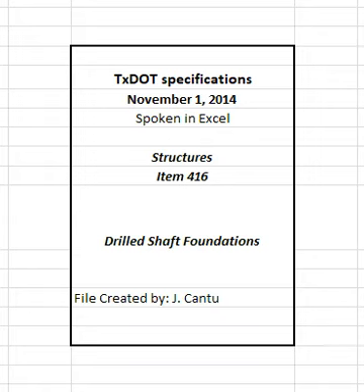3.4 Requirements for slurry displacement method. When soil conditions warrant, use the slurry displacement method to construct drilled shafts unless otherwise shown on the plans. Use this method to support the sides of the excavation with processed mineral slurry that is then displaced by concrete to form a continuous concrete shaft.